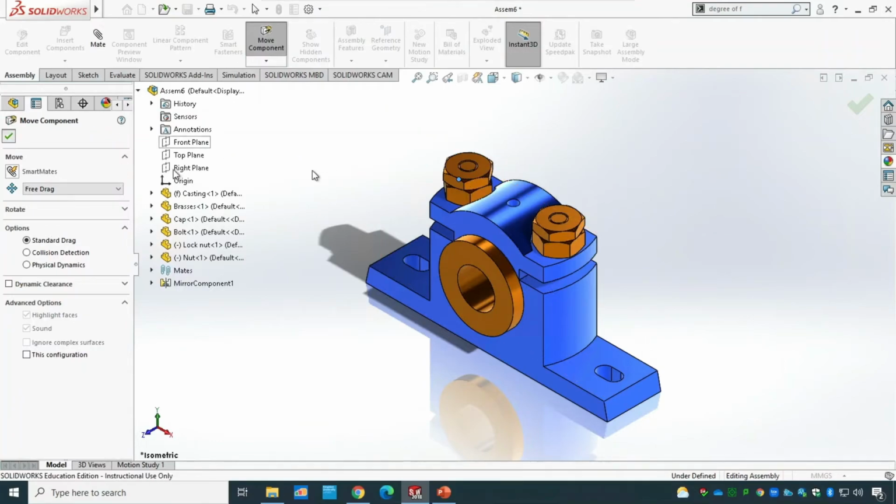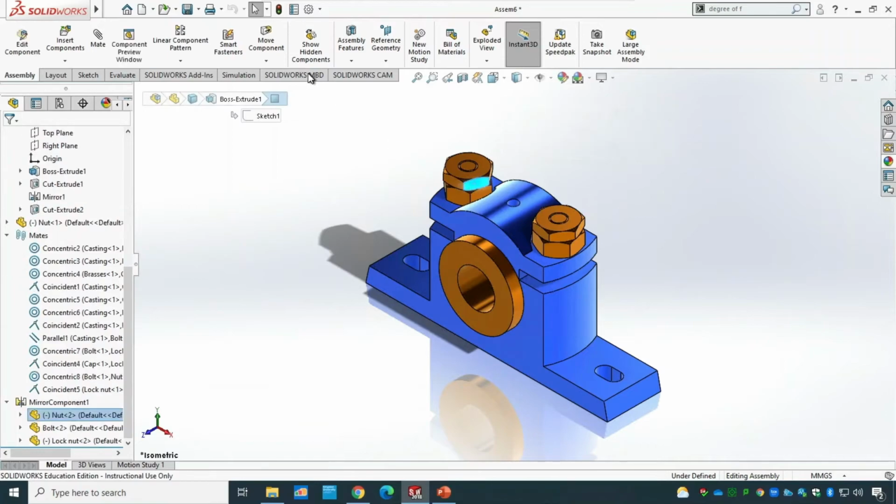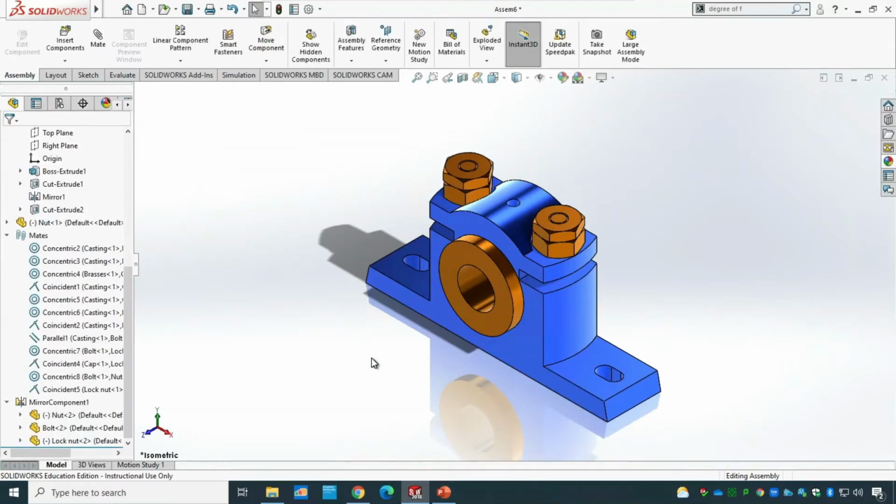And let me double check to make sure the constraint has been applied properly. Let me go and pick that one up here. Let me select the component, for instance, we have here for the moving components, and you can see that it's completely fine. Even for these rotations, if you want to prevent them, as I mentioned, you can easily make them parallel or perpendicular, so then you prevent that kind of movement. But I think it would be absolutely fine to just leave it as it is, because it should perform like that. So that's it. You can see that it didn't take that much.